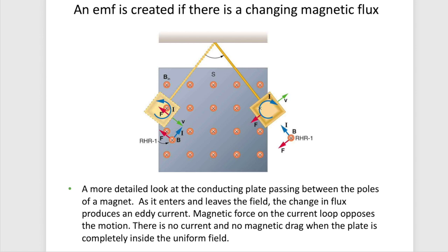The fans that were swinging into a magnetic field in between those strong magnets were not magnetic themselves, but they were conductors, and when they swing into the field, the magnetic field that's affecting them changes, so the area being affected changes, so there's a change in flux, and when there's a change in flux, we get an EMF. And while it's not a loop of wires, it's still a surface area, and it still has electrons that are caused to move with that induced EMF. So we get what's called eddy currents, like eddies in a stream, those little whirlpools on the edge of a creek that you might be playing in.